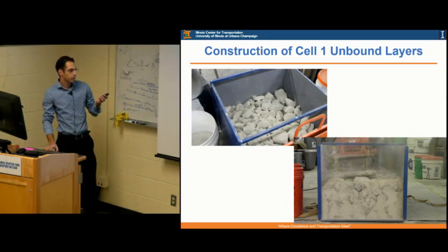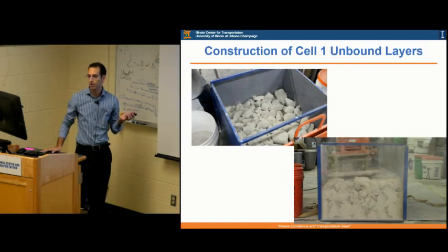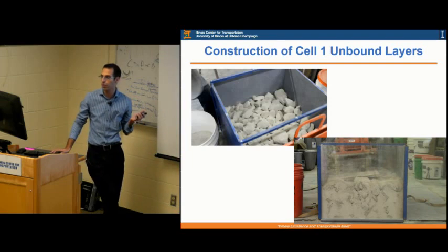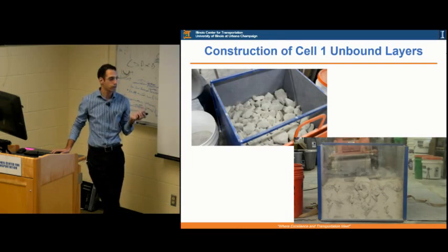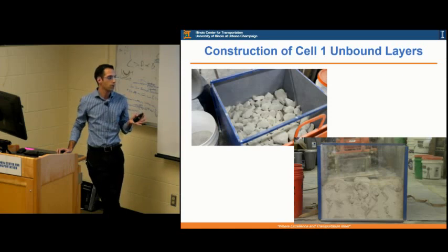The main thing that we got out of this study was that the optimum amount of quarry byproducts that we were able to pack in the case of dry quarry byproducts was around 35% by the weight of the large aggregate, while in the case of wet quarry byproducts, at the existing moisture content of the piles as they were received from the quarry, it was around 25%, and that moisture content was around 2.7 to 2.8%. We also didn't see much difference between building the quarry byproducts in one lift, so filling the whole box and then putting the quarry byproducts on the top, or in two lifts, with one lift of quarry byproducts on the surface and then another lift on the top.